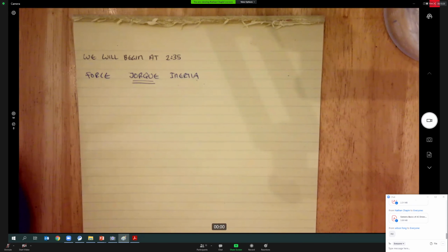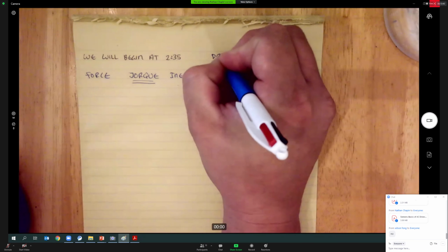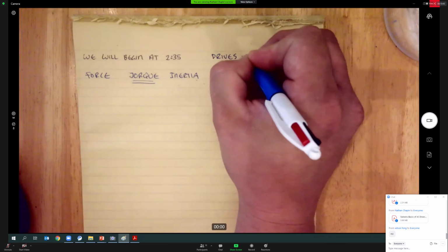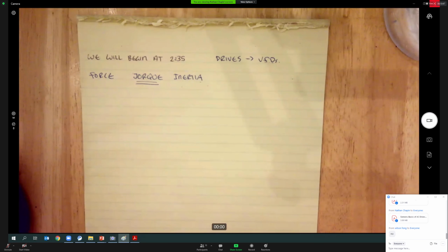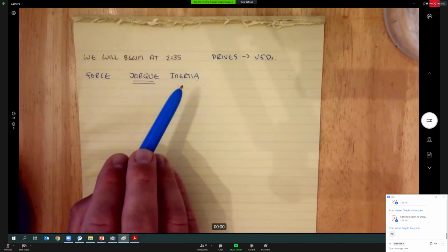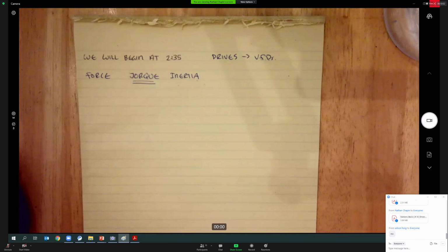So when we start talking about drives, and we're going to refer to different NEMA rotor characteristics, and basically drives haven't completely done away with that. And when I say drives, just so we're all really clear, I mean variable frequency drives, abbreviated VFD. So there's certain load characteristics where if you have a really high, heavy inertia load, the VFD actually needs to be paired or matched with those load characteristics.